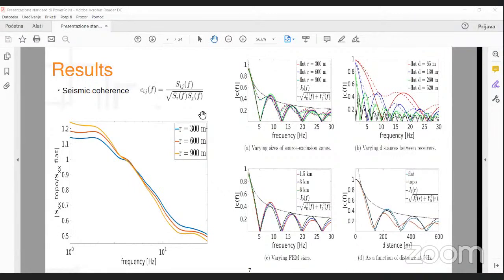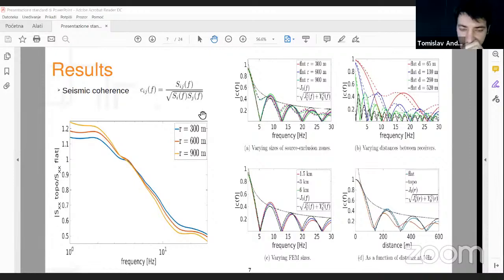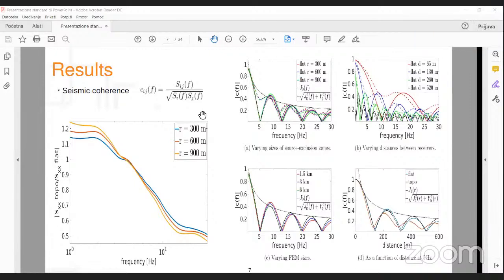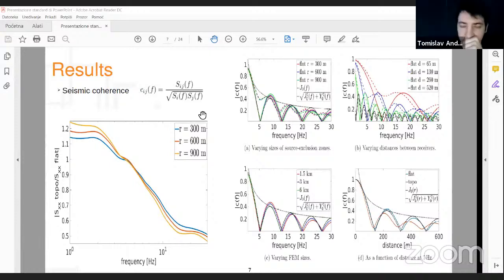So what I mean is the PML, the perfectly matched layer that you put at the boundaries. Yes, to absorb artificial reflections. Right now, I think you just put the same velocities for them as the layers, so that they're completely absorbed. Yes, but I don't think that the CPML cares much about velocities.